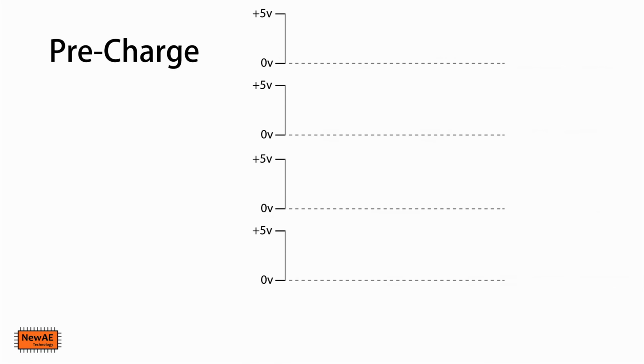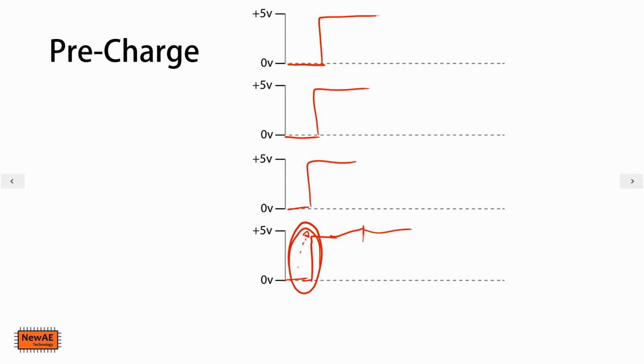Now, there's one extra caveat here. When we go to look at microcontrollers, they do a slightly different thing. We had this state where if you were all zeros with the previous system, and you went to all ones, this would be the worst case. This would be the largest power spike. It also means that this requires the chip to deliver the most power to all of the bus drivers. And every time these switch, they're not always going all the way from 0 volts to 5 volts; sometimes they're staying at 5 volts. But you have to design for this worst case switching here.